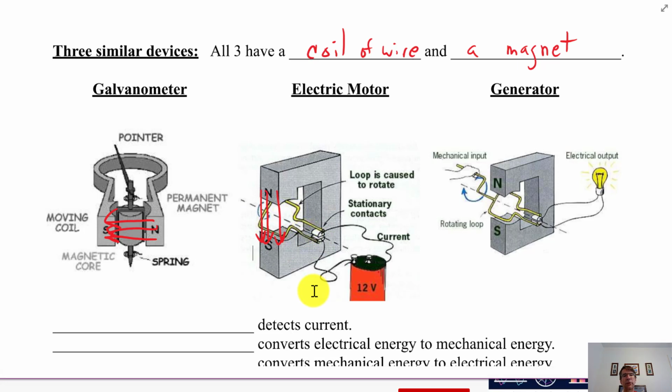We've already calculated torque on a loop because when the current goes through that yellow loop, there's a magnetic field that interacts with the red magnetic field already there. And once again, that creates forces that try to turn that loop. And because of the way it's hooked up with what's called a split ring commutator, which you don't need to remember, it causes this torque to be in one direction at all times. Because if you don't make some fancy connections here, the torque is going to first try to make it turn one way, then the other way, so it won't turn freely in one direction, which is what you want for an electric motor. So you have to have a fancy hookup here.